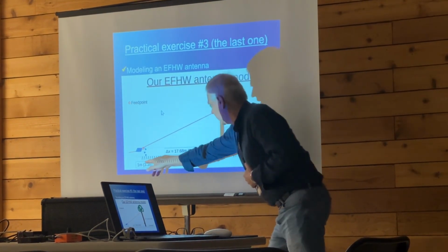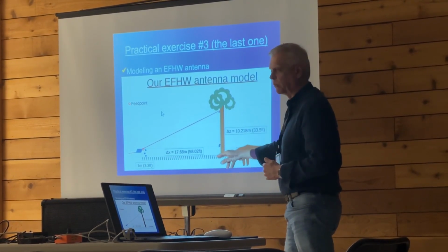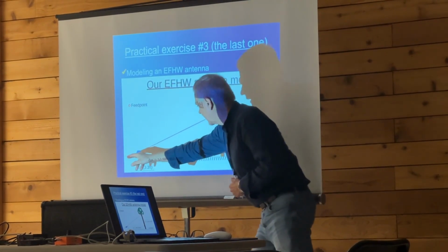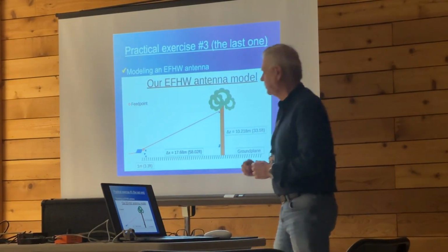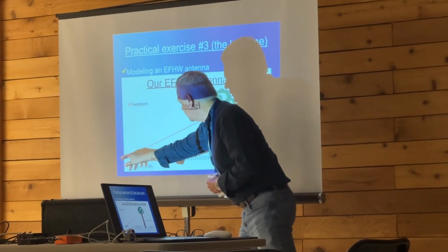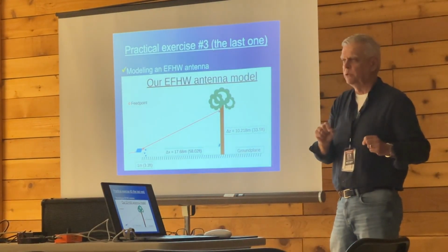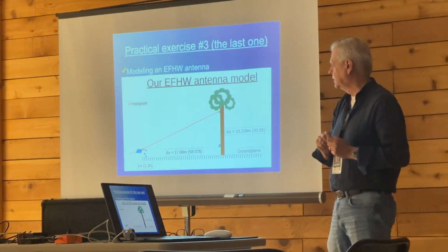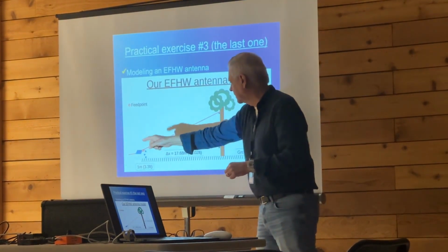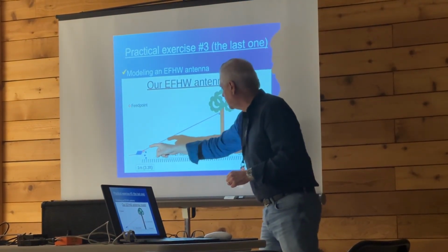Okay, the ground, again, is going to be the hatched area down at the very bottom. This is the best I could do in PowerPoint of a tree, so that's the trunk and that's the leaves up there. That trapezoid over there is going to be the 49-to-1 transformer of the end-fed half-wave antenna. That's going to be a little pigtail, which is really the coax that I'm using in feeding my antenna. Or you can actually have a little counterpoise connected to the antenna. And the 67-foot wire line is going to be this one right here.